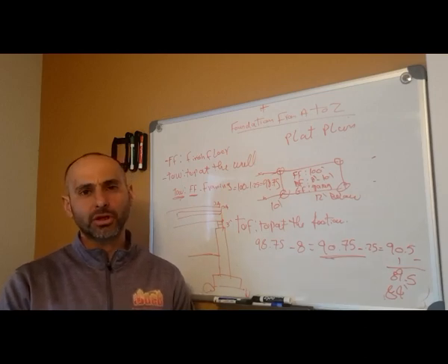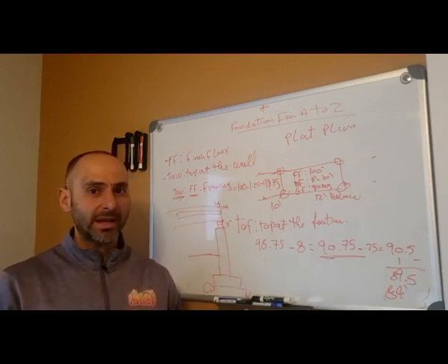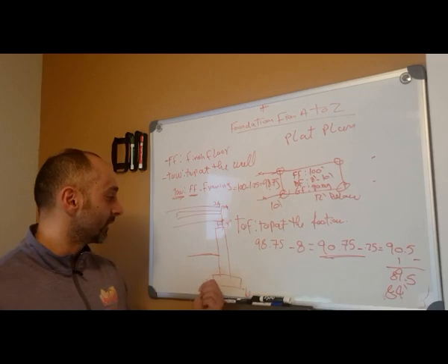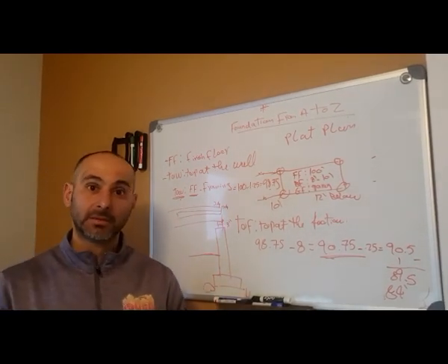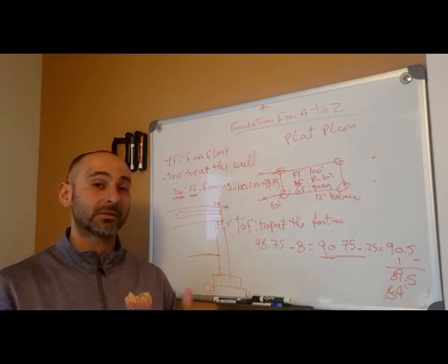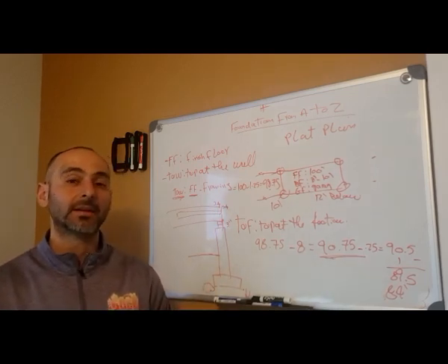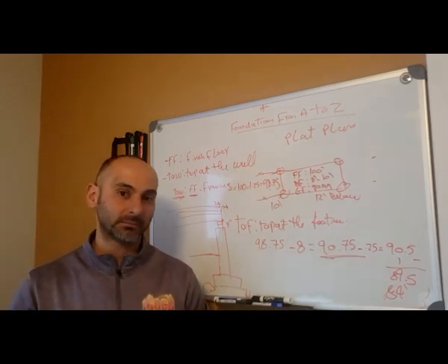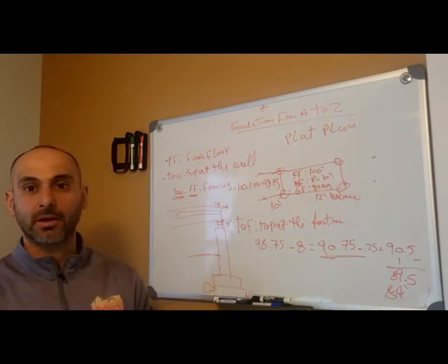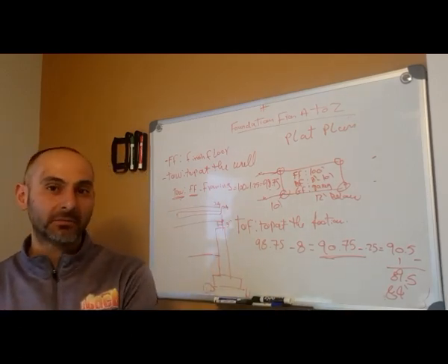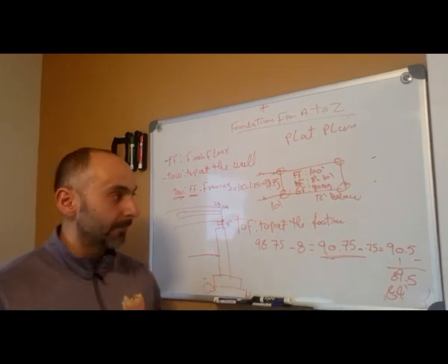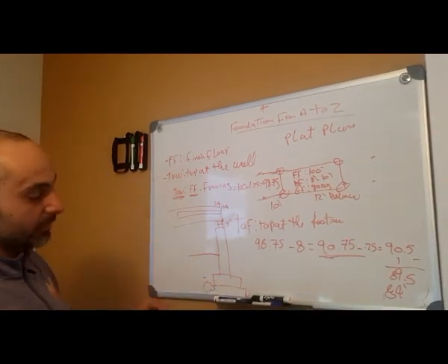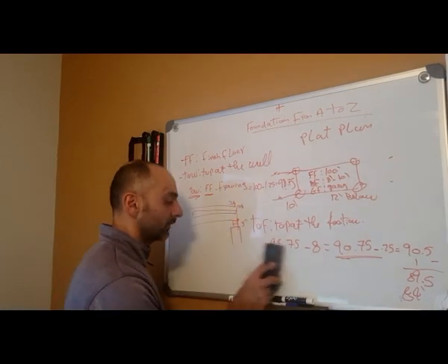Same as the project I showed in the beginning in Verona, where the old house settled 3 inches, because it was wrong from the start. The house after 10 years settled 3 inches from the front to the back, so the whole house is cracked, and there's no way to fix it besides underpinning or other expensive ways. So make sure you do this right from the beginning. Okay, so once you get all these numbers, you get your excavation, and we're gonna go to the footing.